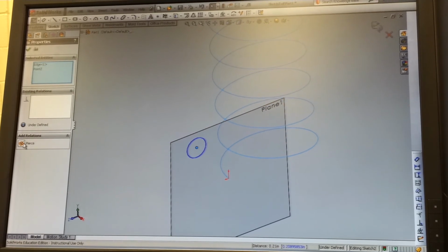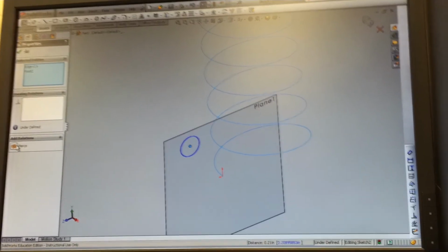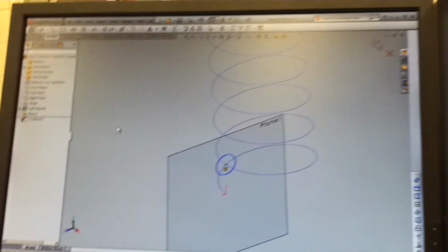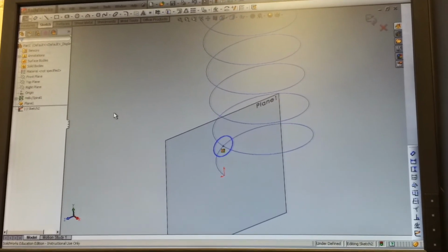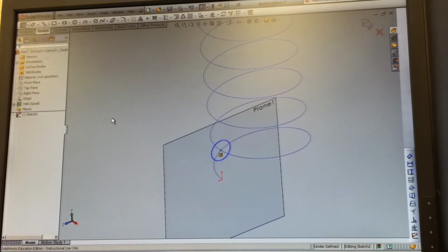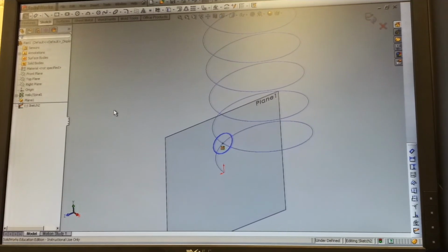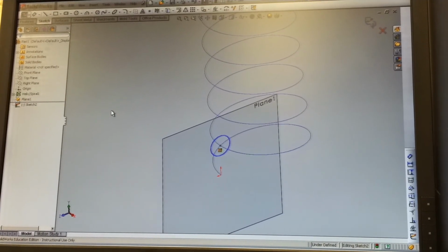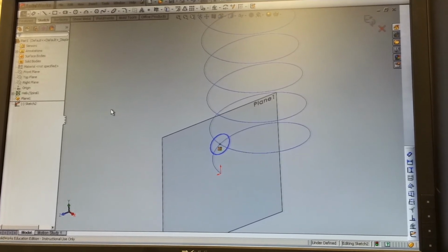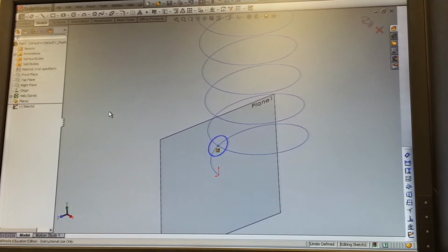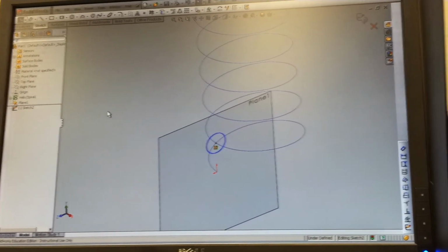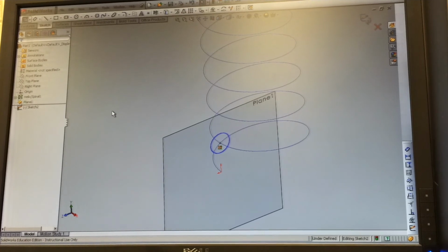And that should bring them together. I'm going to use an option that SOLIDWORKS understands as pierce. What it means is set that helix to pierce through that point. So you cannot make a pierce relationship between two lines. You cannot make a pierce relationship between two arcs. It must be between an arc, a line, or a spline, and either a vertex or a point. It has to pass through something that has no linear or cordial length. It is simply a point in space.